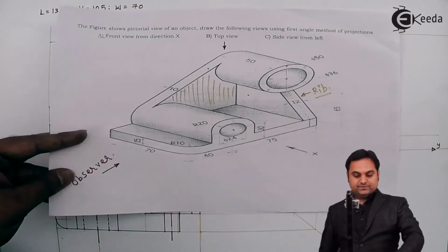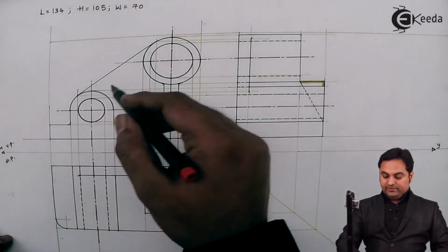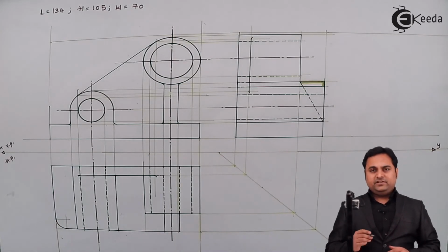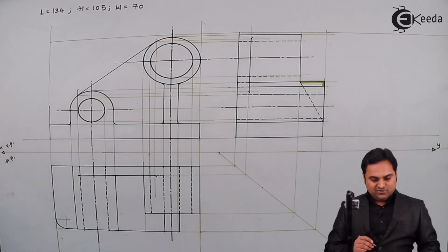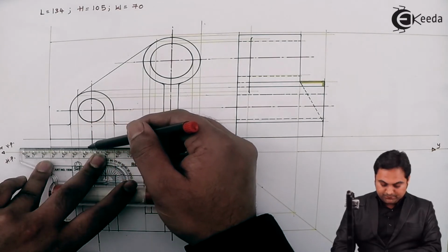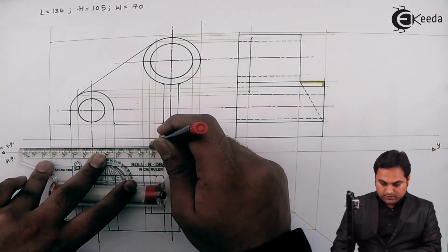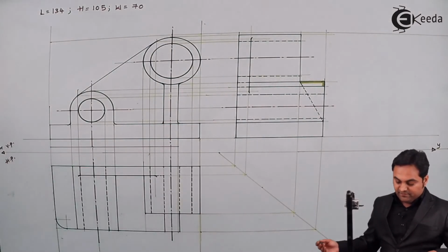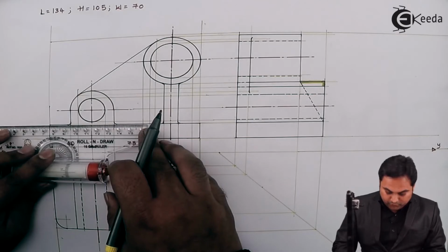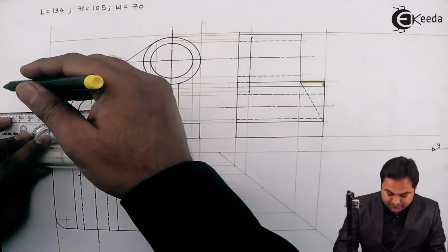Next, I'll give the dimensions, and dimension lines are also medium dark lines. So when we have made the outline with black color, the dimension lines I'm giving in red color, which indicates medium dark lines. So here the dimensions are: from this corner up to the center, this is 40 mm, and then from this center up to the end where the rib is ending, that is 75 mm. The height of the block or the plate, center distance.